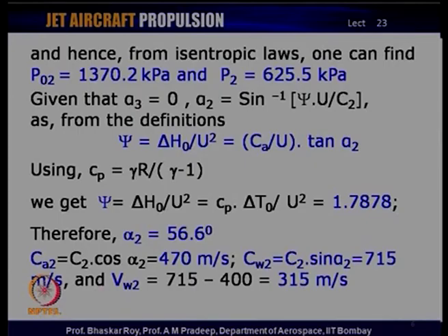Now, from the isentropic loss, we can also find the value of static pressure P2 at the end of the stator nozzle, and since P02 only factors in the 4% loss, it tells us that P2 would be 625.5 kilopascals.